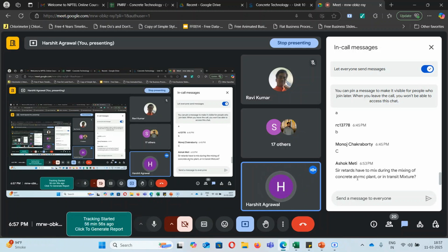So in this way, we need to manage the SP dosage. Now suppose my transportation time is more than what I desired for, then my 100 slump will become 70 or 60 during pouring, which I don't want. So that's why we need proper engineers who can control my concrete. Before it is taken out from the agitator truck, we can add a little more SP to increase my slump back to 100 for pouring. So that's how RMC operates.